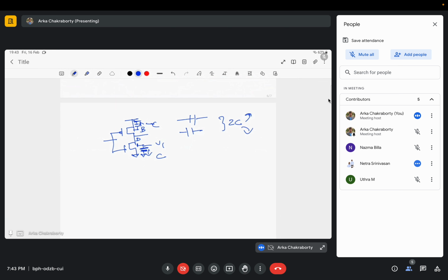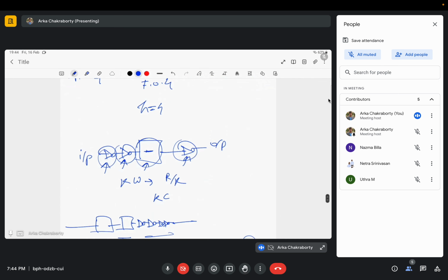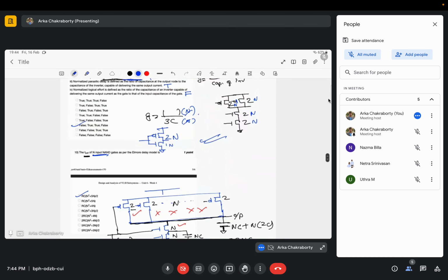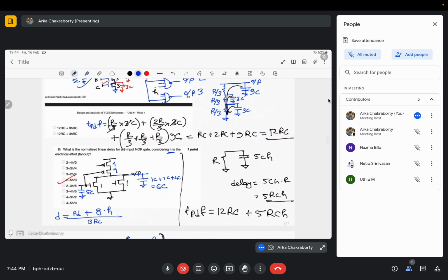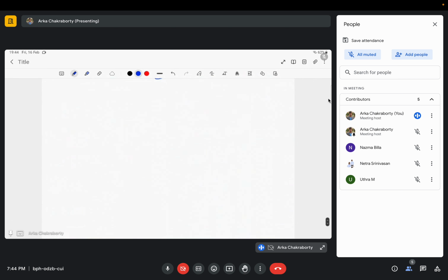I might not have seen all the lectures, so I don't know. I think in contamination delay he was talking about an inverter or a NAND gate or something like that. Inverter, okay. Generally it's easy to understand the contamination delay in terms of NAND gates. You have to discharge these parts also. If they are already considered discharged, it is considered as contamination delay, else it is considered as propagation delay. But using an inverter, it might be thought that we also need to discharge these body capacitances.